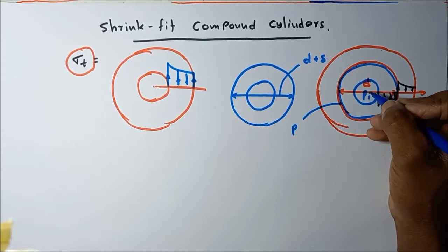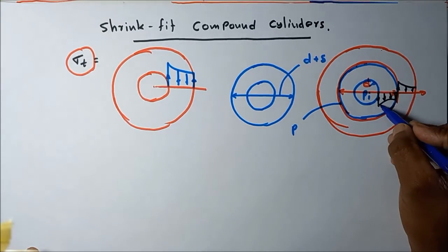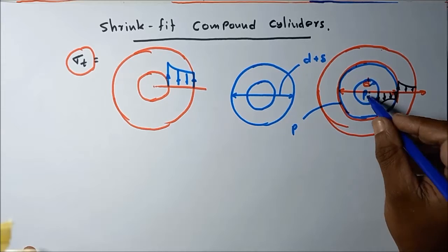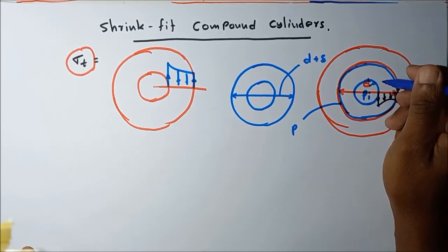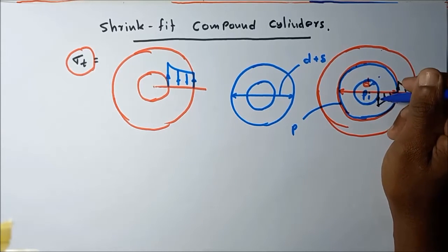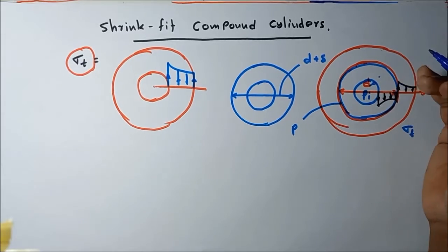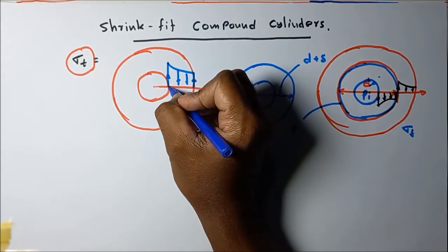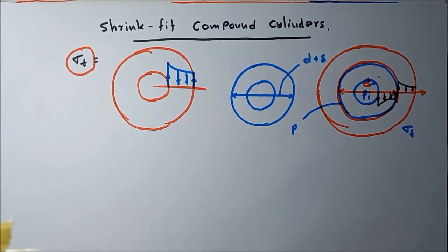When the cylinder is subjected to internal pressure, the increase of sigma t starts from the negative value, so it can take a higher load, and does not reach the maximum failure limit, because it has negative residual stress. In the single cylinder situation, it does not start from zero here it starts from the negative.